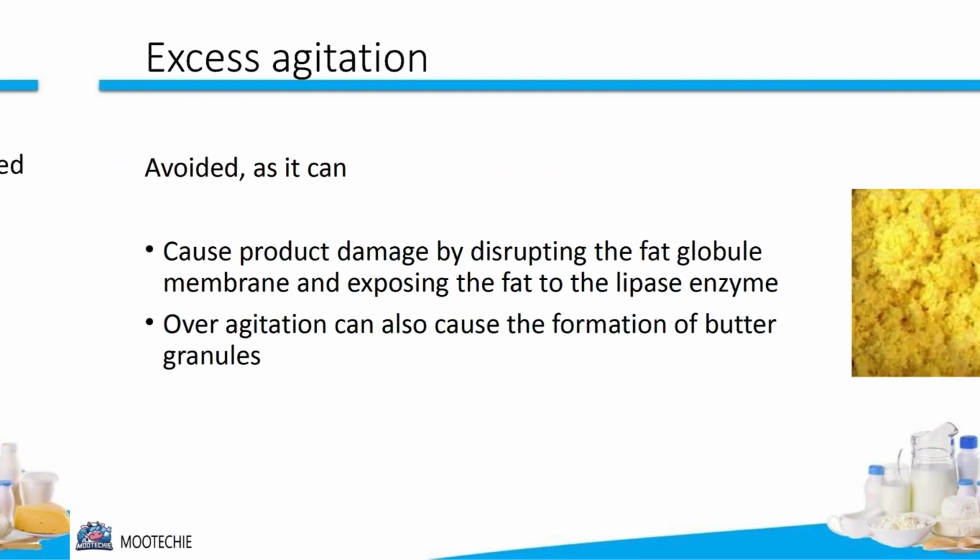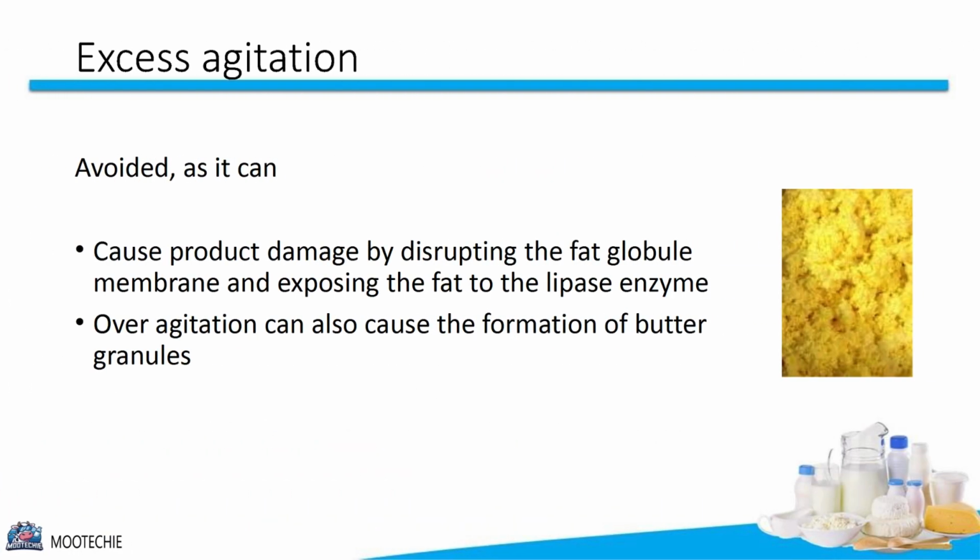While agitation is necessary, excess agitation must be avoided. Over-agitation can cause product damage by disrupting the fat globule membrane in milk. This exposes the fat to the lipase enzyme, which can lead to rancidity. Furthermore, over-agitation can cause the formation of butter granules, which is undesirable in most liquid milk products.